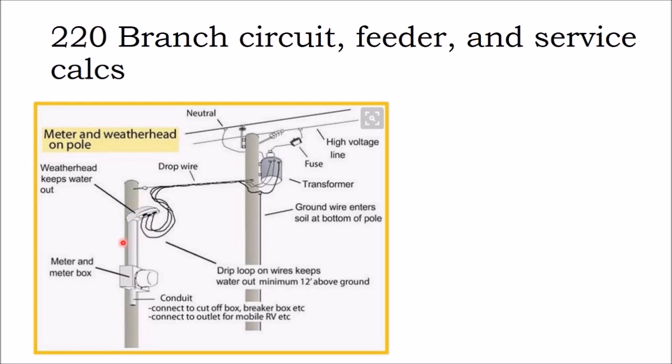Now, that problem exists in the solar industry too. You have cables going into an electrical box on the rooftop, and when I came into the industry, I didn't know that I had to put a little drip loop on the cables going into the box. That's something they teach in electrical training. I didn't get that level of install training in any of my solar classes.